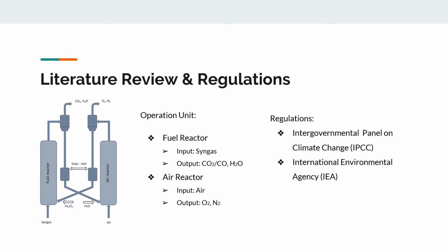Based on a variety of literature that we have reviewed during this project, a common chemical looping combustion usually involves the use of a metal oxide as an oxygen carrier, making a closed cycle between two interconnected reactors of the unit. There exist certain criteria for the oxygen carrier relevant to environment, thermodynamic properties, reactivity, etc. After much consideration and researching on various literature, we are using ilmenite as oxygen carrier in our project.